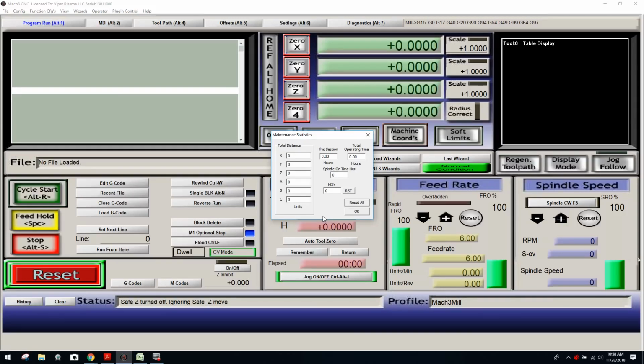For my guys that are dealing in the smaller equipment and transitioning into CNC, this is a feature you want to start using immediately. If you start noticing a timeline, you can also use that recorded timeline to document if you find loose screws, if the motors need servicing, or the length of time spent cleaning the machine. It's a very, very easy timeline to establish and very easy to go back and reference to service the equipment.